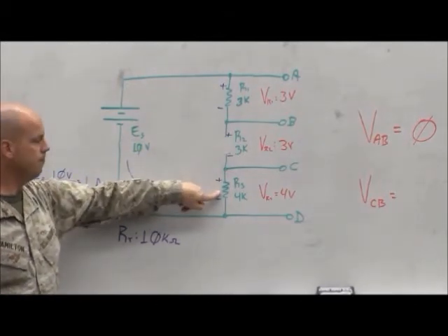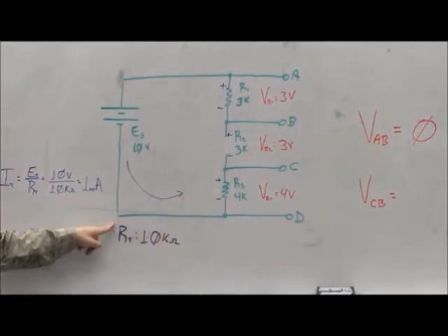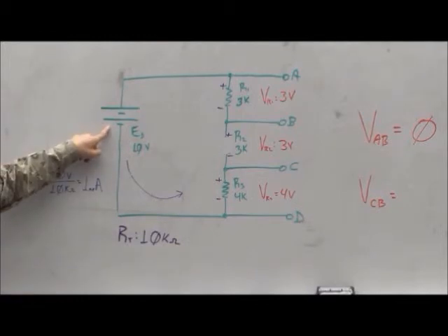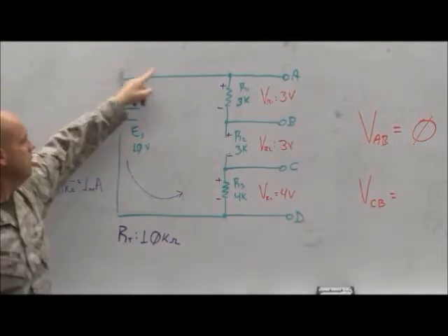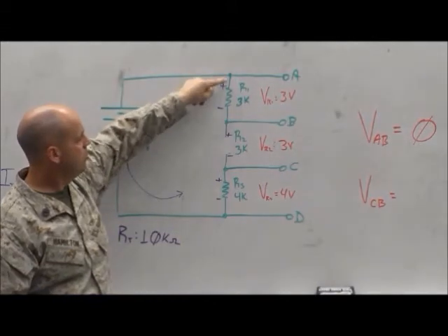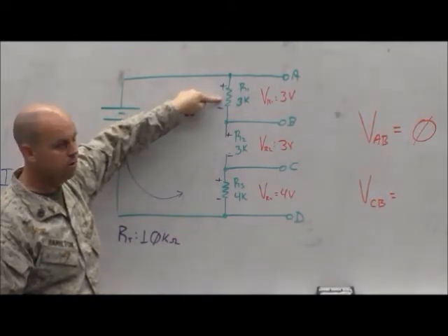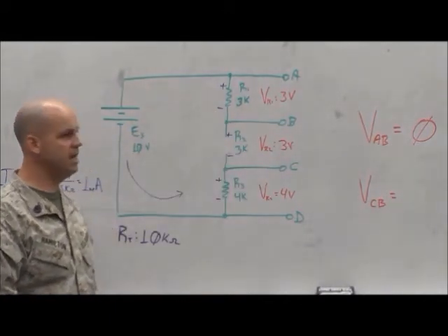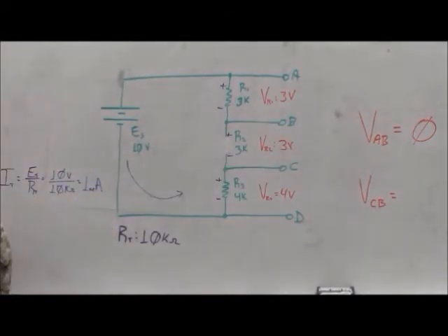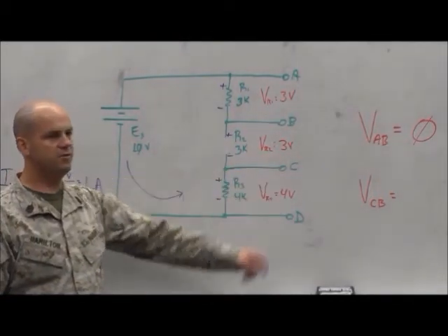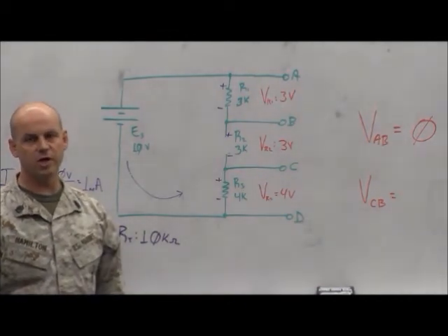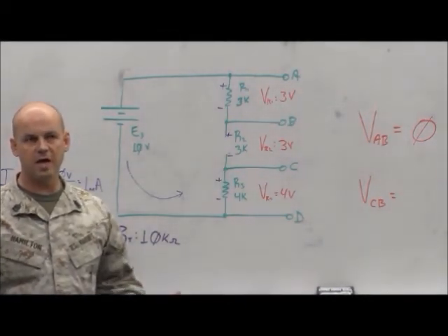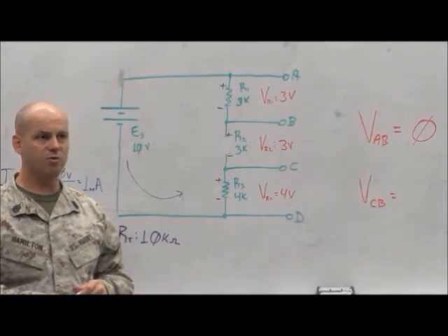0 volts, right? Down to the node. Across, up, what do we get? Negative 10, over. Do we hit any voltage here? No. Up, node, there's B. So what are we sitting at? Negative 10. Did it increase or decrease? It decreased. What were we at before? Positive 3 volts. So the difference of potential there was an absolute value of 3 volts.